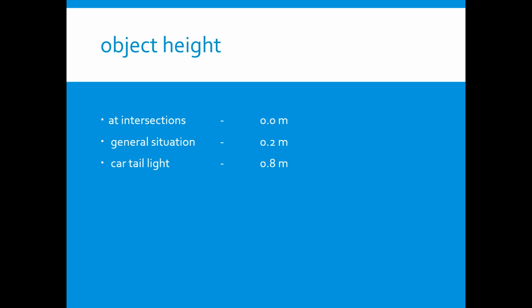However, at the required stopping sight distance for high speeds, small pavement variations and small objects, especially at night, may not be visible to most drivers. Thus, most drivers traveling at high speeds would have difficulty in stopping before reaching such a small object. The length of vertical curve required at a crest increases significantly as the object height approaches zero, and the general figure adopted, which provides satisfactory design, is between 0.2 meters and 0.6 meters.